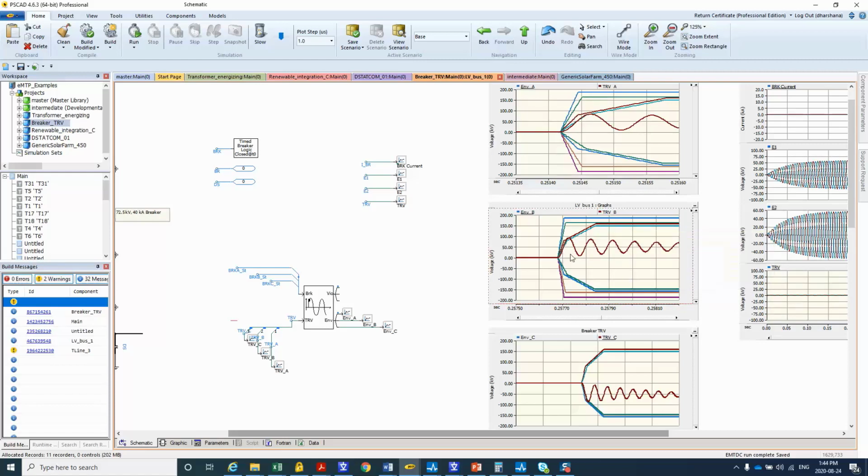These line segments I have drawn correspond to the capability of the breaker. We don't want to go into details, but what you have to ensure is that the actual voltage is within the relevant line segment, or the TRV capability envelope. So those are two very common traditional type EMT study examples.